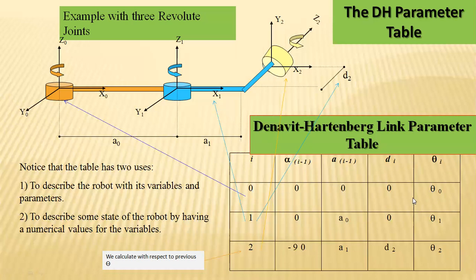In this way, we assign the values for our DH parameters, the 4 parameters. At each and every joint, we need to represent these. At joint number 0, we have only the rotation part, that is theta naught. The theta naught may be 30 degrees, maybe 60 degrees, through 360 degrees, and either clockwise or counterclockwise is possible. Hence it is represented with theta suffix 0.